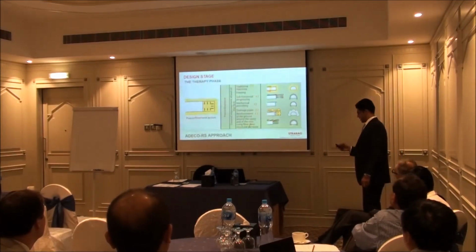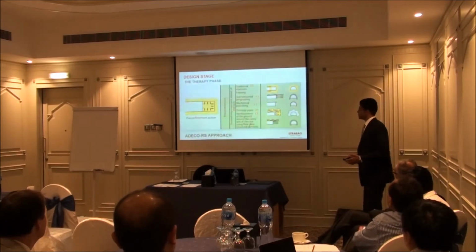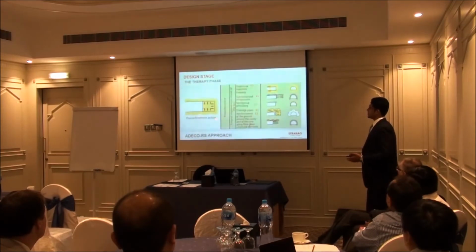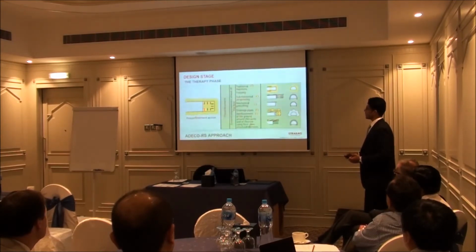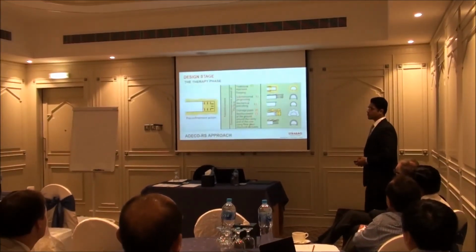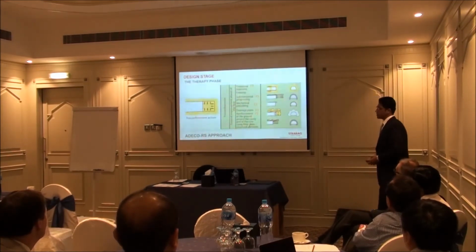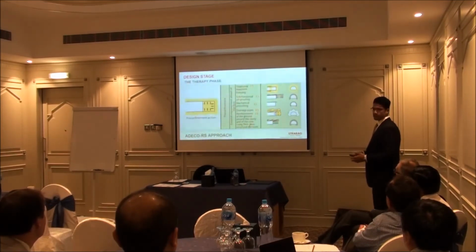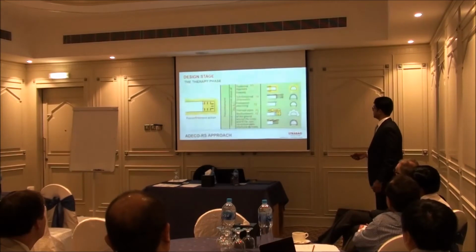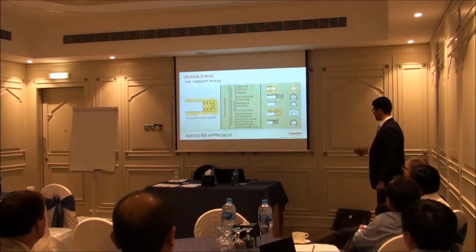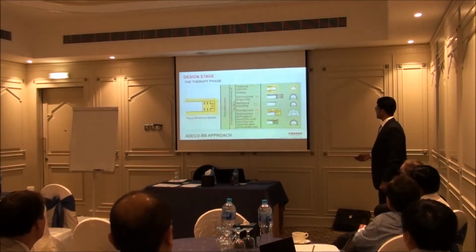In the therapy phase, they then prescribe what type of measures need to be taken. The measures can be in the form of pre-confinement or confinement. First, we see what is pre-confinement. Pre-confinement is stabilization or intervention in the advanced core itself. So the tunnel is advancing in this direction. We can improve this advanced core by traditional injection, freezing. These are only some of the methods listed here. Sub-horizontal jet grouting, as was discussed earlier, mechanical pre-cutting around the profile of the tunnel, and drainage pipes to drain any water from the inside out. Reinforcement of the ground cavity by using fiberglass structural elements, as was seen in the tunnel in Italy before.